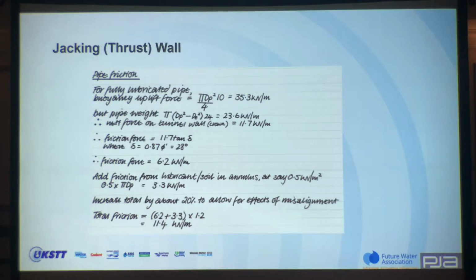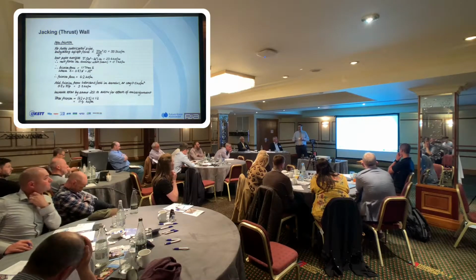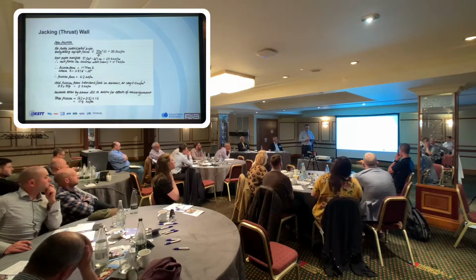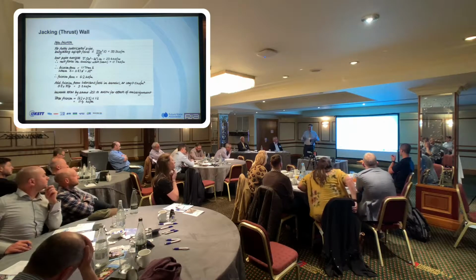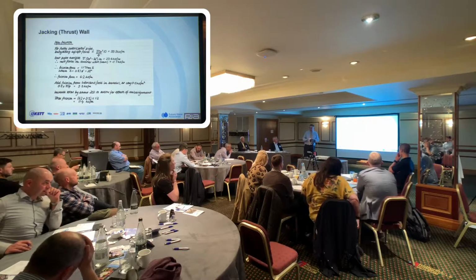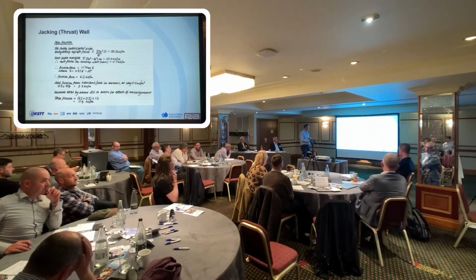Just be mindful of the friction factors, because I've had it before where you might do a drive and then the loads go a little bit higher, and then people will start looking back and quoting the guidance. The 0.5 to 2.5 tonnes per square metre, as we mentioned earlier, is a general guide. It's a bit empirical, if you like. It's based off experience. You will get much lower loads, but by the same token, you could get much higher loads.